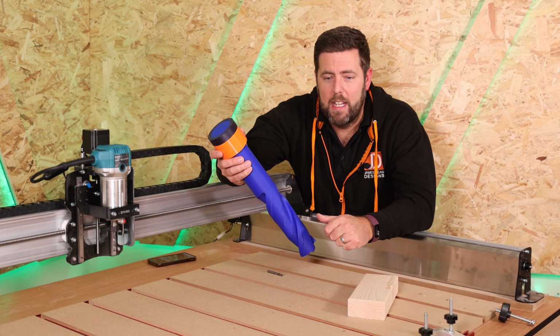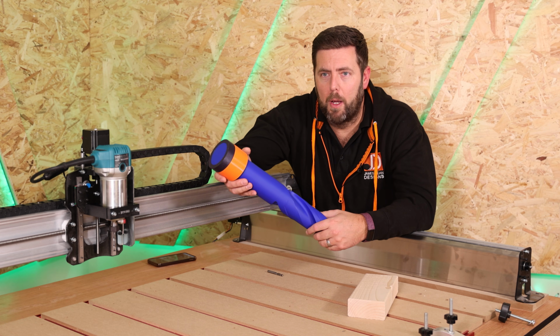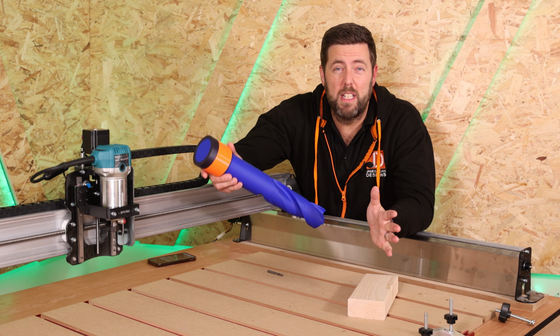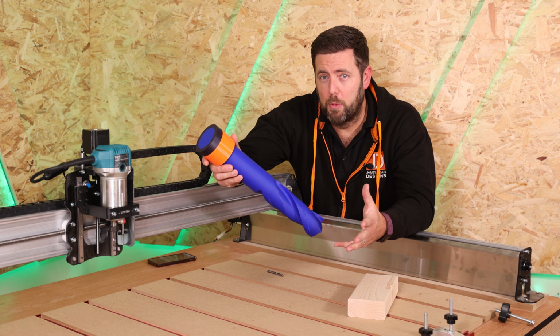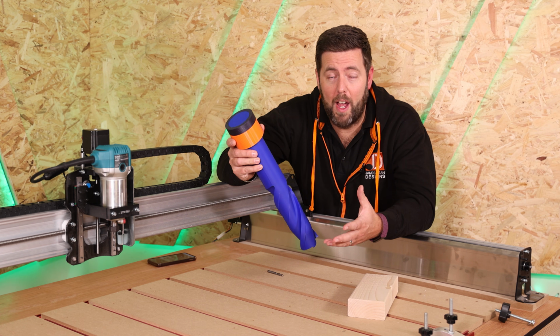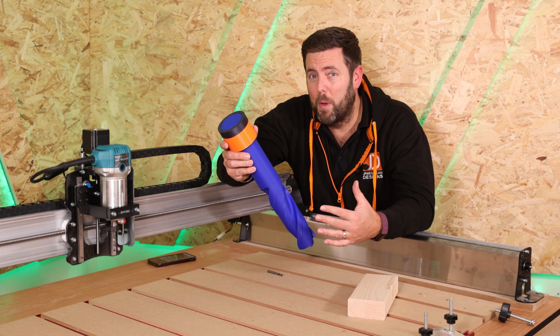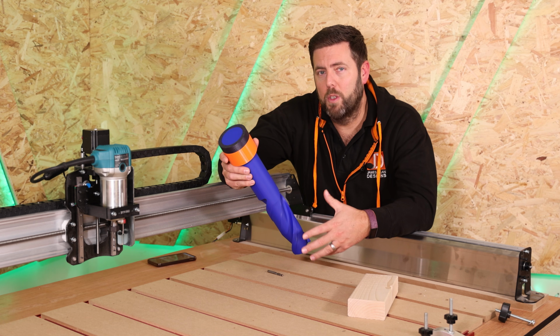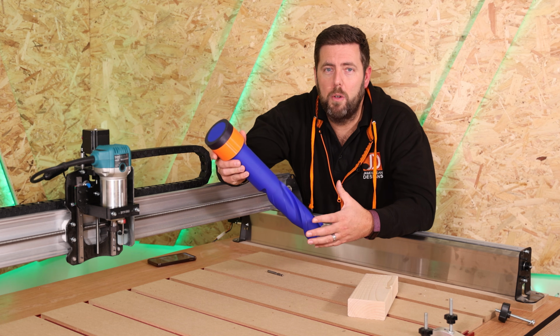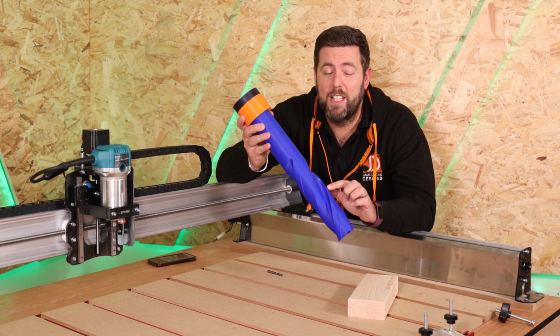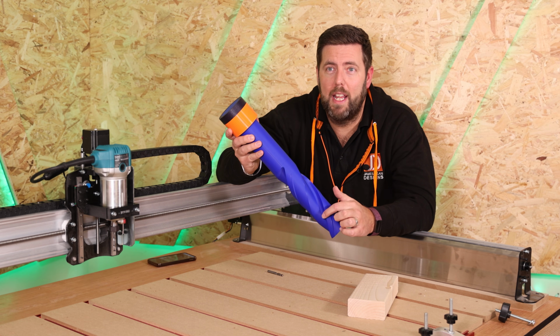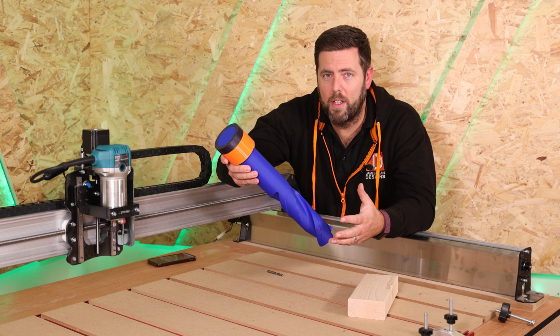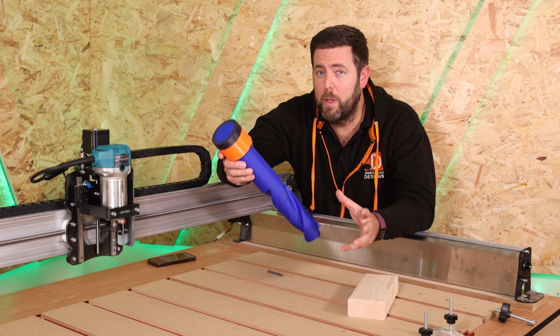Now, as I keep saying, it's all these things that make it feel very difficult to find this correct rate for your bits. When we are talking about chip load, there is what we call an ideal window. A lot of people don't realise that if your bit is going too fast, it will overheat. But equally, if it's going too slow, it will also overheat. And whenever your bits start to overheat, you're effectively dulling them and losing the cutting edge, which means they have to work harder to do the same job. And that's what we're trying to avoid.